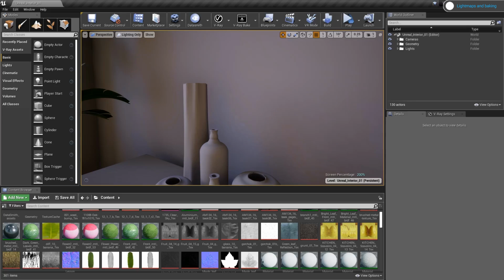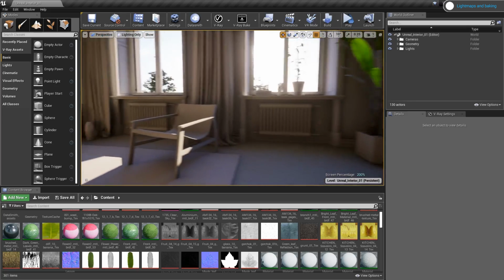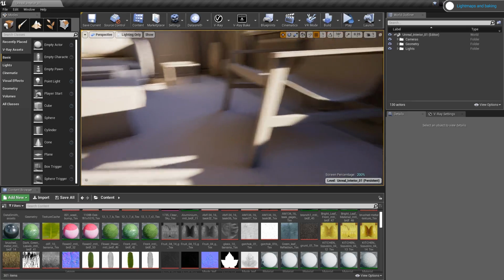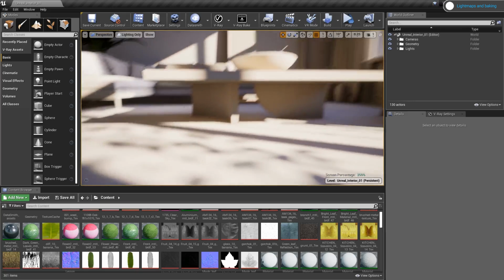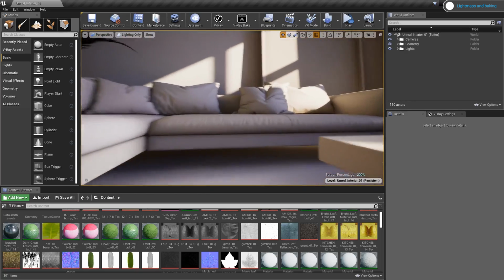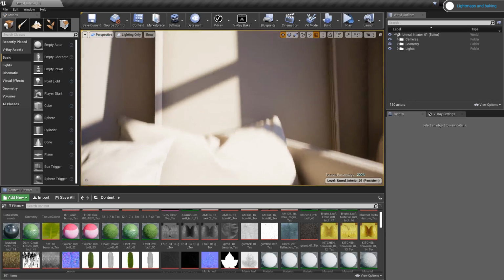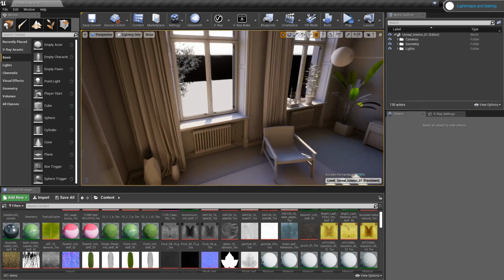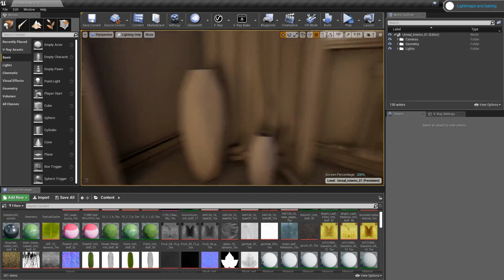It's important to note that every time you change your light map's resolution, V-Ray will automatically find a space in your atlases for your light maps by rearranging them automatically or creating a new atlas for it if the resolution is too large. In the near future, you will be able to export your light maps baked with V-Ray from Unreal and even edit them in external applications. But keep in mind that they will be 32-bit floating point textures.